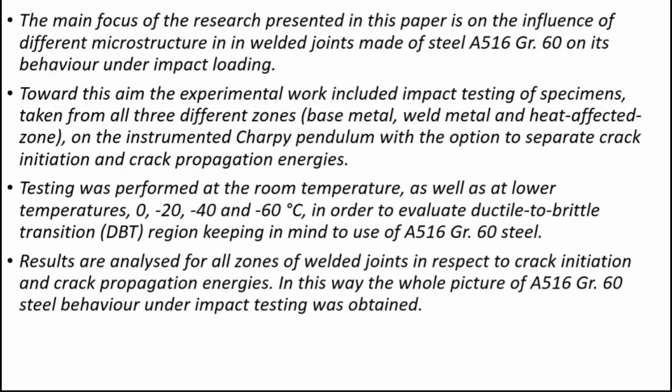It was almost irrelevant because we actually tested these welded joints starting from room temperature down to 0, -20, -40, and -60. The idea is to evaluate the ductile to brittle transformation temperature.